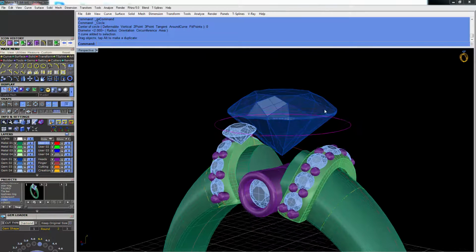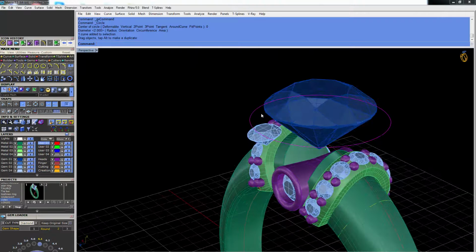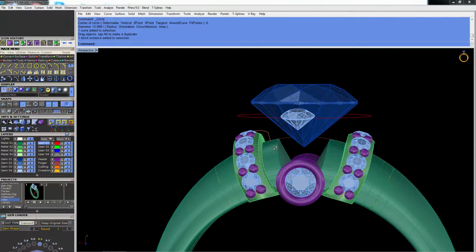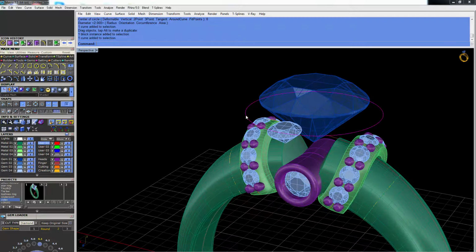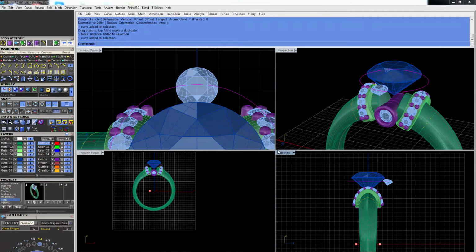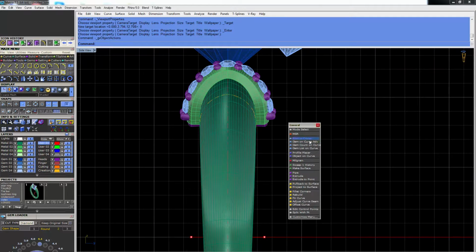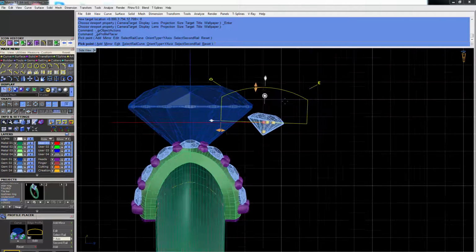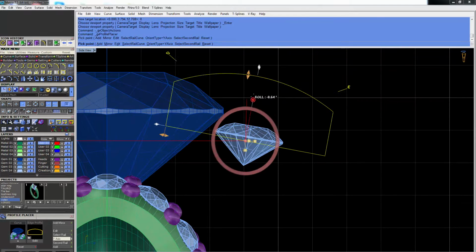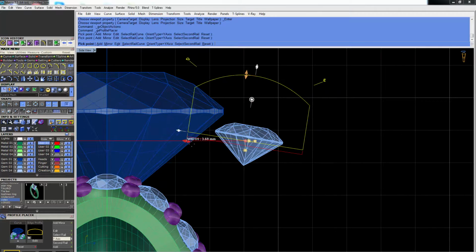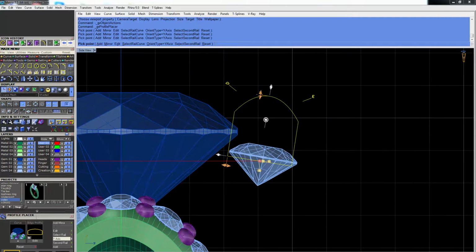What I'm going to do is basically, the halo is going to hold this gem. I'm gonna create some claws that are going to hold the actual halo. Okay, so now if I select that curve, I can just F6, not F5, profile placer. So I have a profile. I will make those gems smaller, they are quite big. I'm gonna make it completely flat.